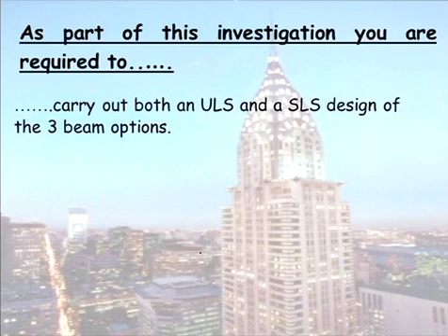So in Project 1, you said deflection isn't that important. We'll just do a strength check. Now, as well as a strength check, you have to do a deflection check because beams tend to deflect more than trusses.